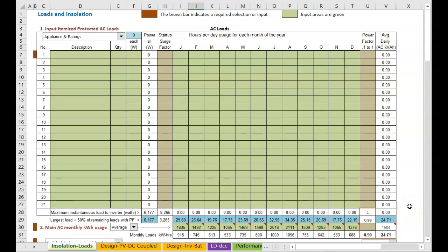When using the PV battery configuration tool to design with self-consumption, we typically look at the home's total usage and select a percentage offset. Most of these systems are also AC coupled. So we're going to look at two things here: AC coupling and self-consumption. If you're doing an off-grid standalone system, it's recommended that you itemize everything. You go down through all these different rows and columns and set your usage for your various appliances.